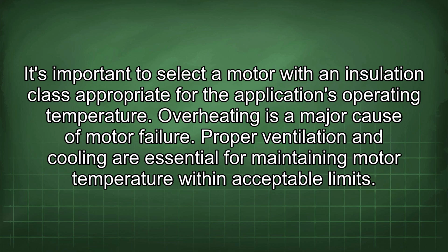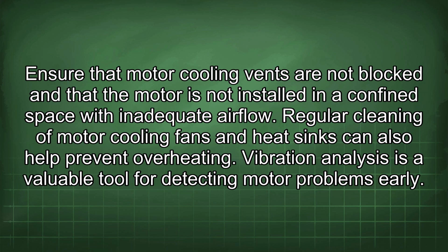Overheating is a major cause of motor failure. Proper ventilation and cooling are essential for maintaining motor temperature within acceptable limits. Ensure that motor cooling vents are not blocked and that the motor is not installed in a confined space without adequate airflow. Regular cleaning of motor cooling fans and heat sinks can also help prevent overheating.